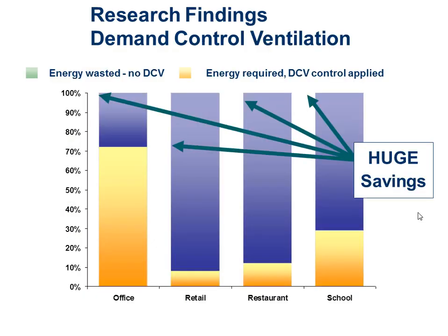In some of these given spaces, there's also often a pretty large savings that can be associated with that. For example, in office buildings, you can see here, I'm seeing a 25 to 30% reduction on average, and this was based, these 4 charts are based on average data, I want to say from like year 2000 to 2004 or something like that. But it's similar profiles that you would have now. So instead of ventilating to 100% occupancy, I'm able to ventilate at 70-something in the office building for a couple different reasons. One, everybody doesn't show up all the time, right, which I think you would believe is accurate. And 2, certain spaces aren't always occupied, like the training room or things like that.